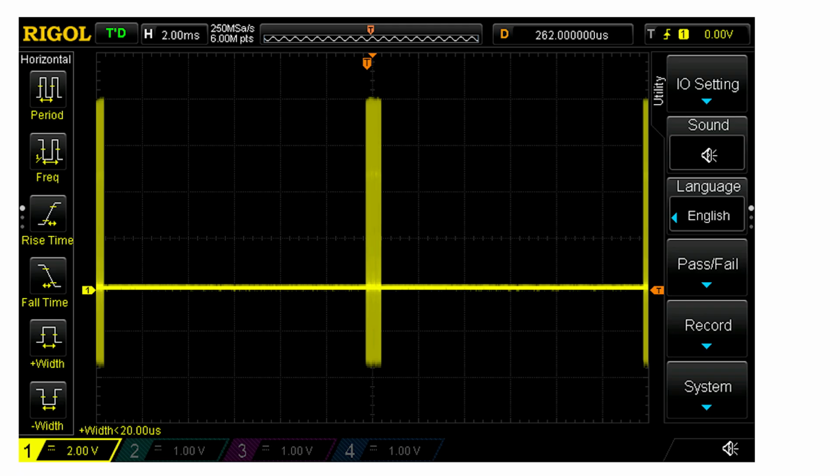And that every 12 milliseconds is why there's a 72 frames per second frame rate, because I can squeeze 1024 of those NeoPixel data into that half millisecond between the two pulses. And that timing is critical.